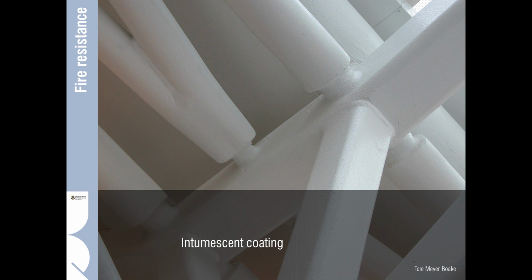Now, this intumescent paint is a high build surface finish. It comes in a limited range of colours, and it's not a very aesthetically pleasing finish. It can be used for some structural steel in exposed situations, but typically in very large buildings like airports and stadia and so on, where the steel is quite a distance away from normal vision, so the actual visual appearance of the intumescent paint is not noticed.